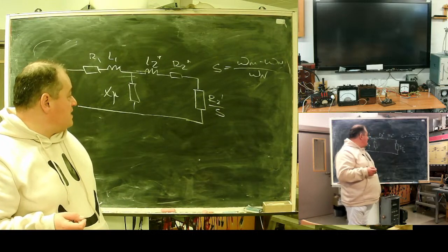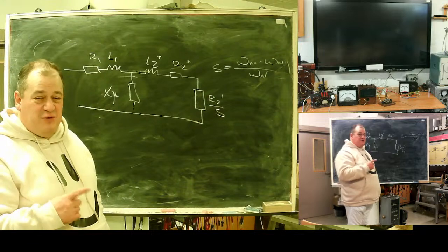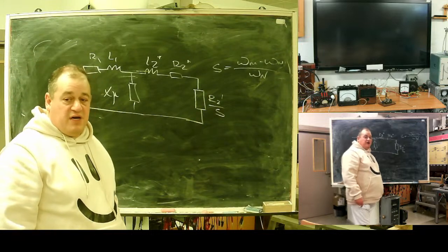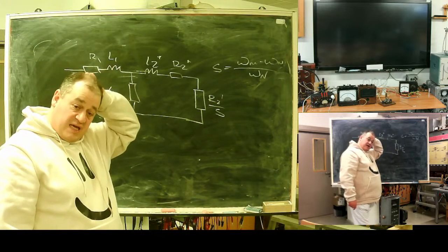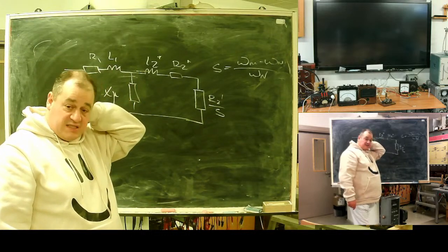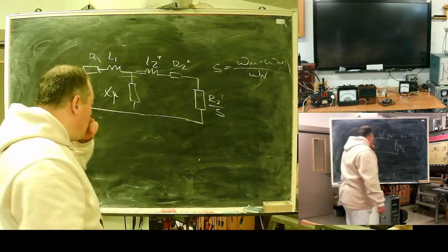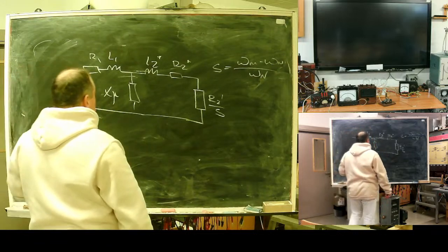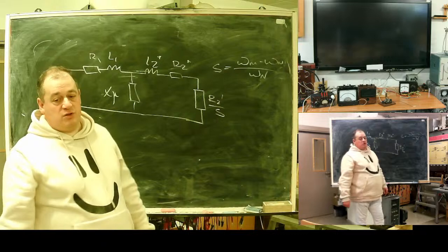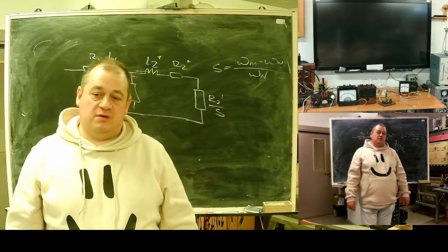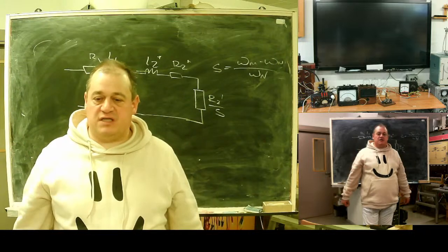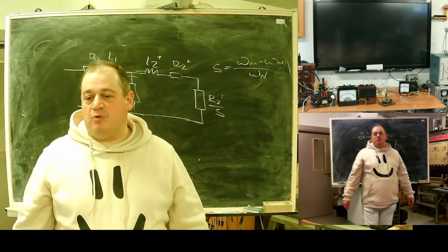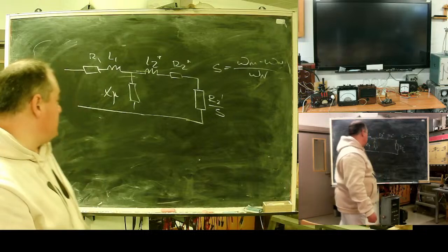For direct sequence, if you need very precise data for the transient, take into account that your asynchronous machine in the first milliseconds of the transient will supply your network with energy.